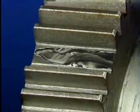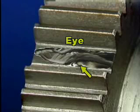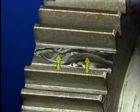When a gear tooth breaks due to fatigue failure, the appearance of the break will usually contain a circular pattern in the metal called an eye. During fatigue failure, a break slowly works its way across the tooth, and when the pressure gets to be too much, the tooth breaks off.